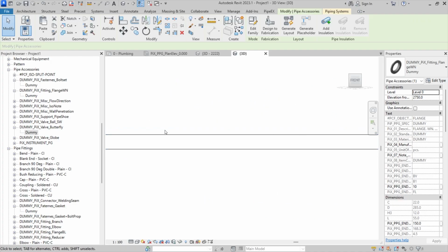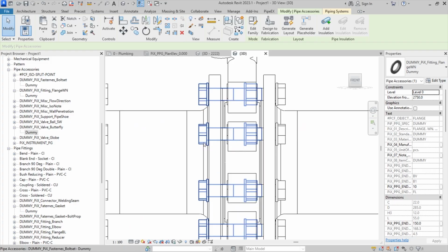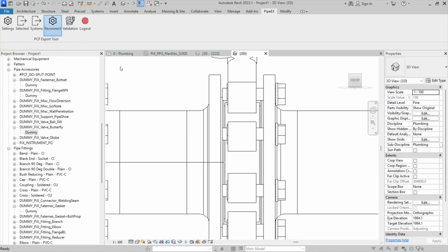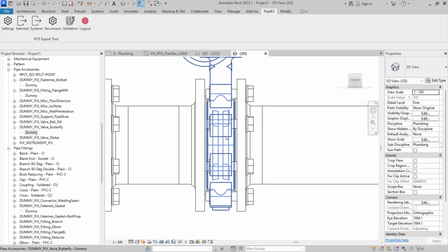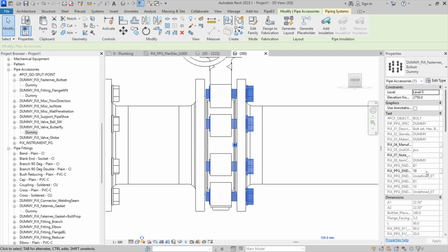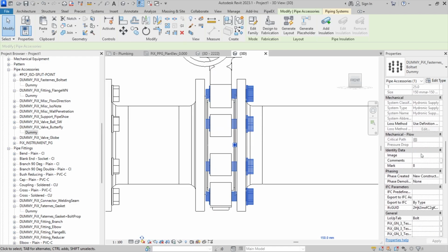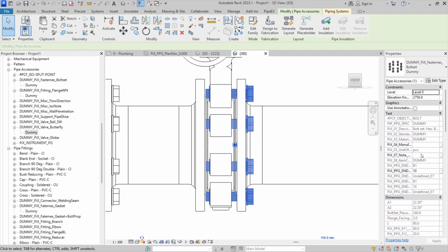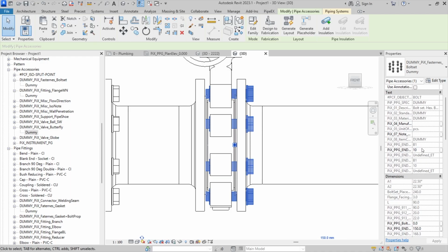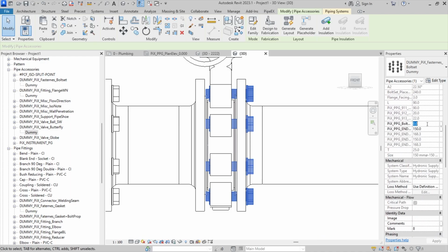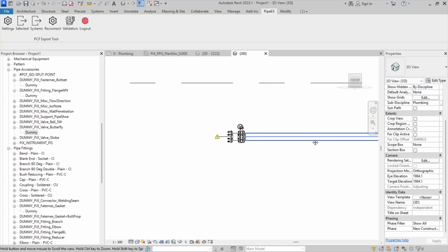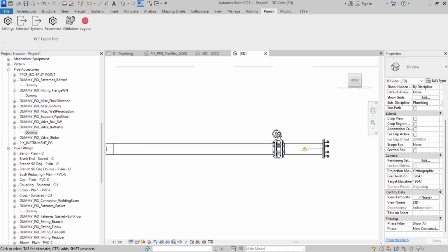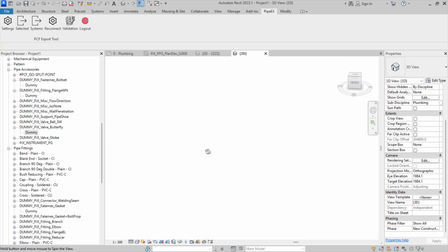We are done from one side. From different side we're going to do the same. So we're also just deleting the bolt sets, then reconnecting the components and making our bolts a bit longer. I cannot see the property. Yeah, it's over here. So it will also be 140. And here it is. Next step will be to add a few supports.